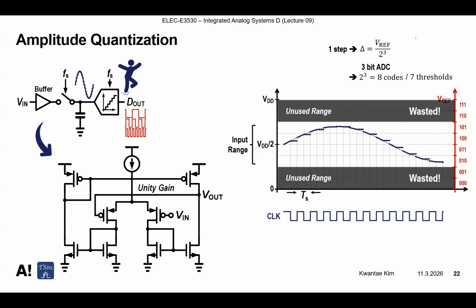There is always a certain amount of millivolts, for example, 10 millivolt or 5 millivolt, sometimes 100 millivolt, limited to VDD minus 100 millivolt or VDD minus 10 millivolt, and on the lower side, 10 millivolt or 100 millivolt. Because we are building op amps or whatever analog circuits using PMOS and NMOS, that requires some amount of output DC range at the transistors, at the VDS.